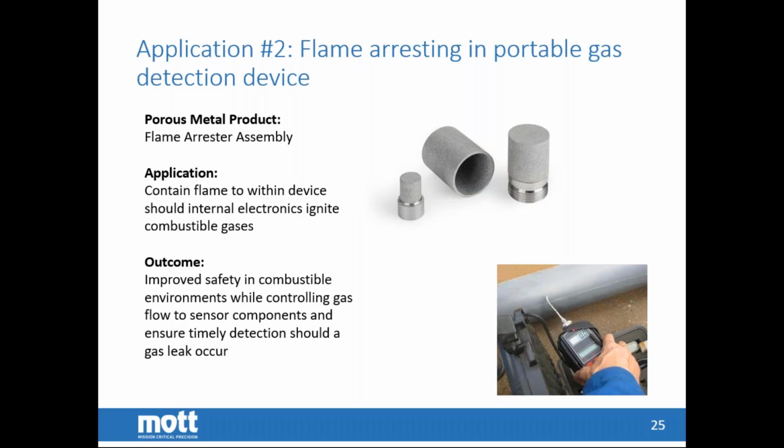Exactly, and I do know of several new applications for specific inline piping as well in some of these areas, when you have an inline flame arrestor. I'll comment on one quick trend before we move to the next application, that I do see a lot of customers moving to finer and finer detection limits. So it's actually an important design consideration to look at the absorption of that potential thing you're trying to sample into the media before it hits your detector, whichever mode you're operating, catalytic bead or the like. So all important design considerations we factor into when we do flame arresters here at Mott.